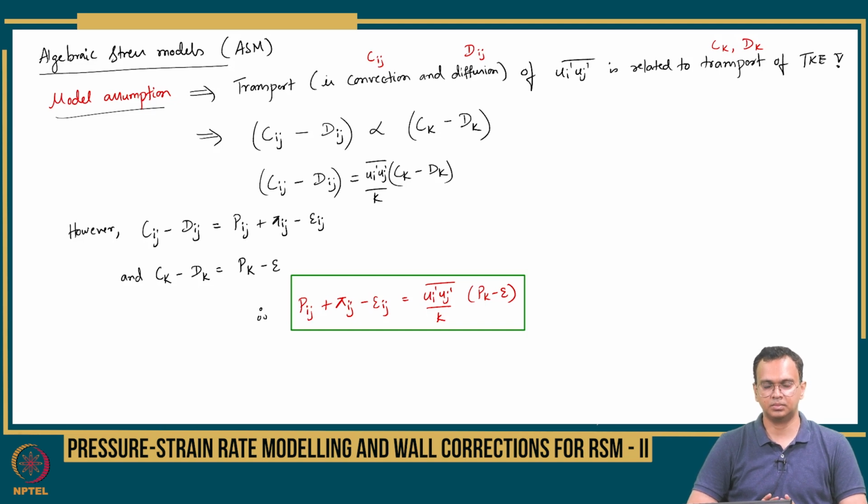But now we can say that I am more or less completing the statistical approach in the modeling, right. So statistical modeling had RANS equations, solving RANS equations. That means we are interested in mean velocity and mean pressure. To get that, we are modeling the turbulent terms. We are lumping it as Reynolds stresses, and Reynolds stresses are either modeled using an eddy viscosity approach or solving transport equations for it. But the main objective is to get mean velocities and pressure. If that is your focus, that is a focus for industry, this is sufficient. Of course, you have to live with some error there.